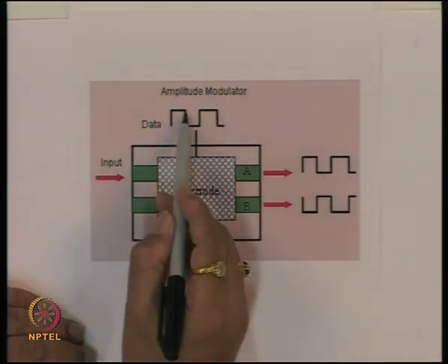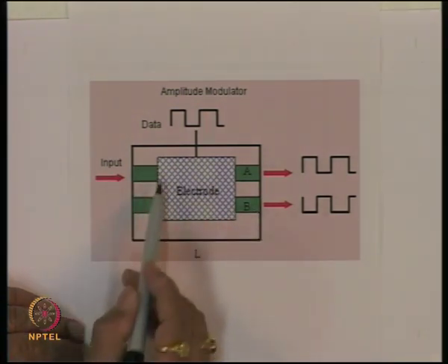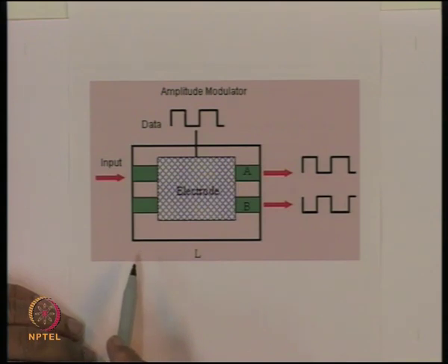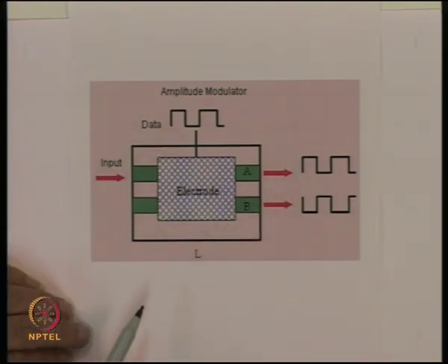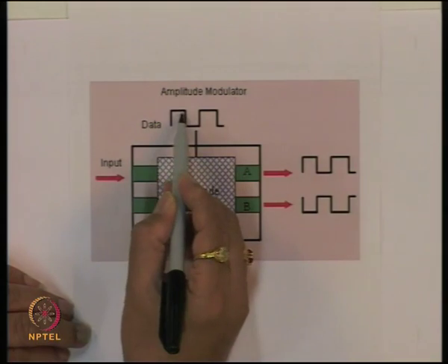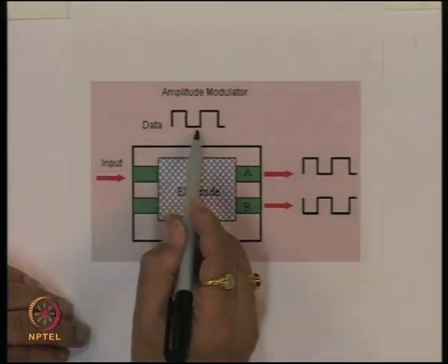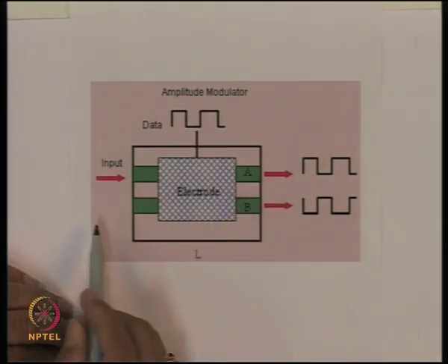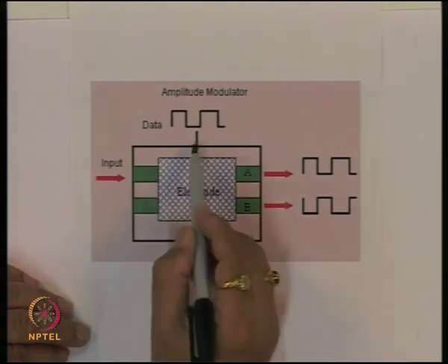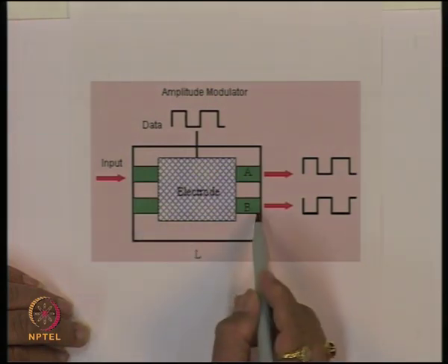Then when this one is applied, you will see that the signal will get connected to this, the whole power will get transferred to the second waveguide, or vice versa, depending upon the characteristic which we have. So, for one of the states, the power will get connected to this waveguide. When the other state comes, the power essentially comes back to the second waveguide. So, by switching now the voltage across this electrode, we can connect the power here or here.